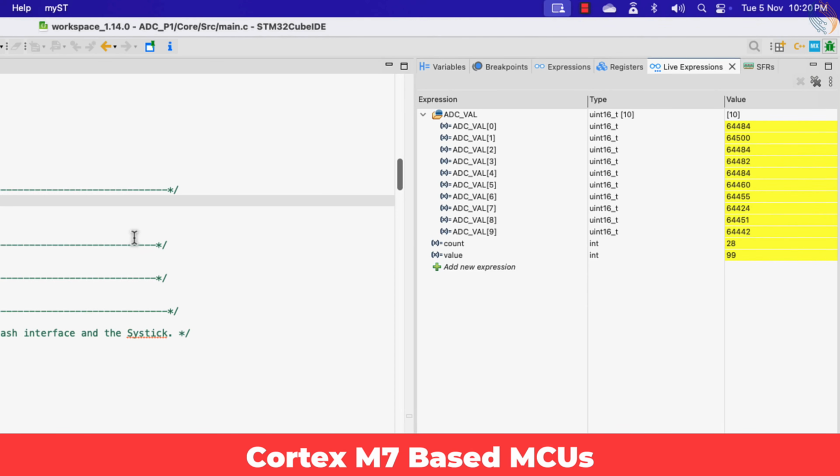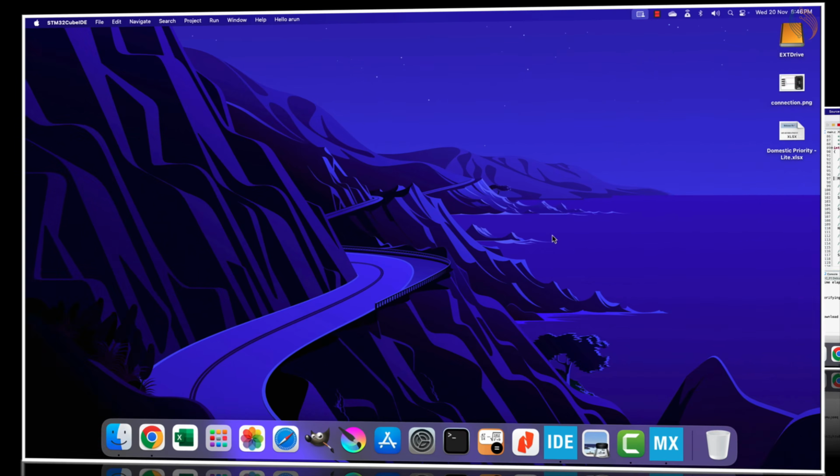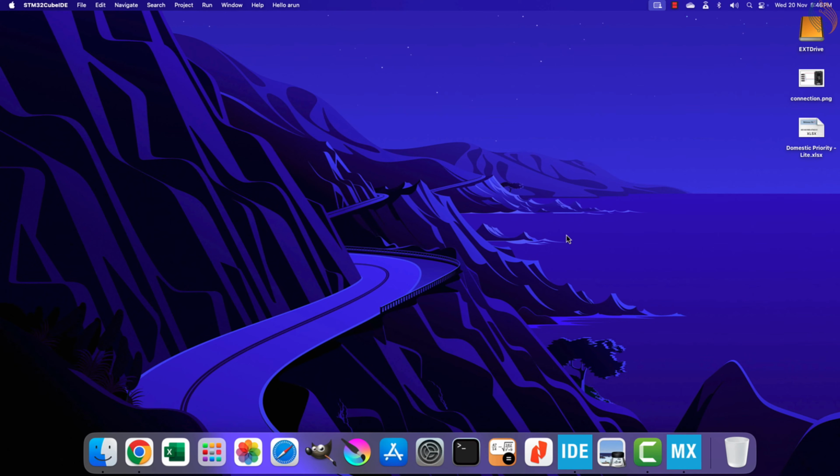I hope you understood how to use the interrupt and DMA to read a single channel of the ADC. Today we will start covering the multiple channels of an ADC. We can use polling mode and interrupt mode to read multiple channels also, but the ADC configuration varies across the devices. While I was testing it across different MCU series, I needed to make a lot of adjustments to make it work. Therefore I decided to cover multiple channels using only the DMA mode. Here the DMA mode does not mean that the conversion will continue forever, and the interrupt will trigger at a continuous rate.